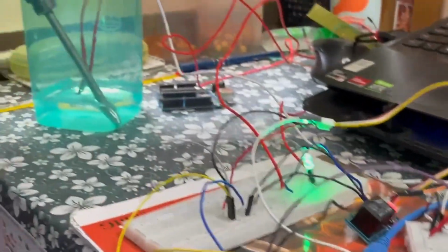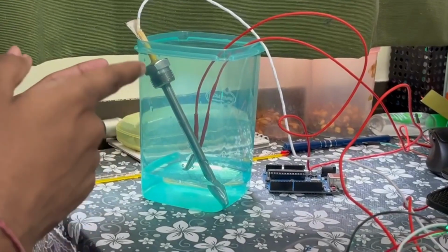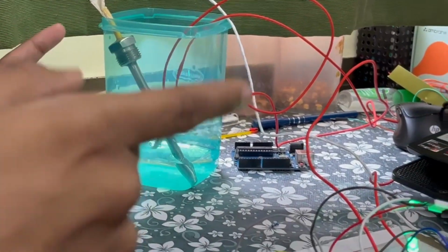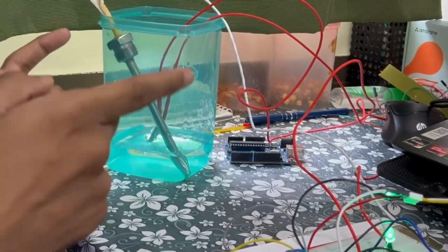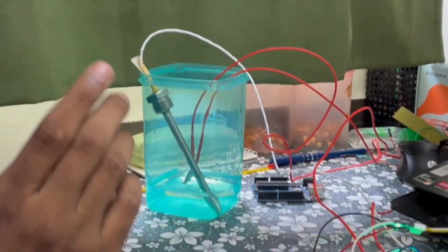Hey there, I am Prayas Kulkarni and I will be explaining the working principle of our project. We are using a relay pin which acts as a switch. This is an RTD PT100 sensor which measures the temperature of the water. So when the measured temperature reaches a threshold which we have set to the mark of 35 to 40, it cuts the power to the heater.